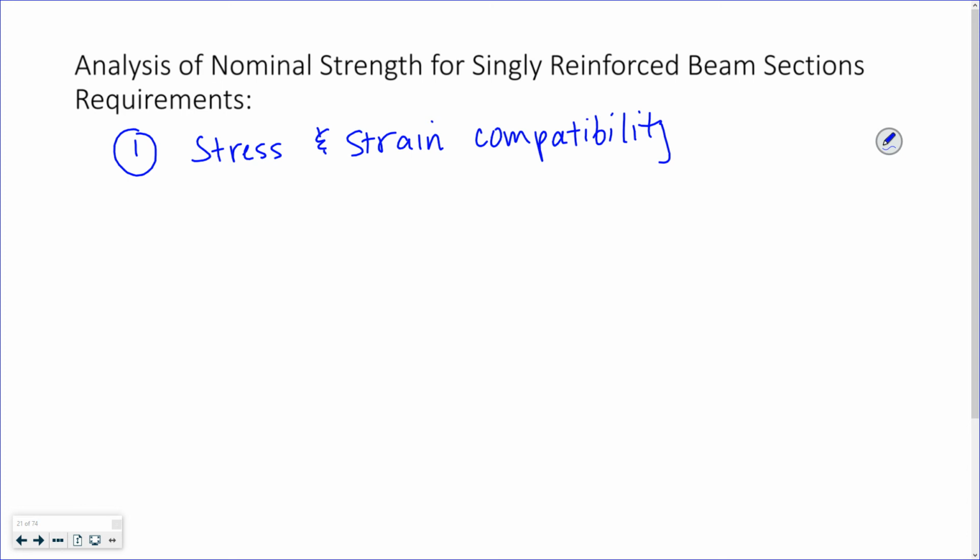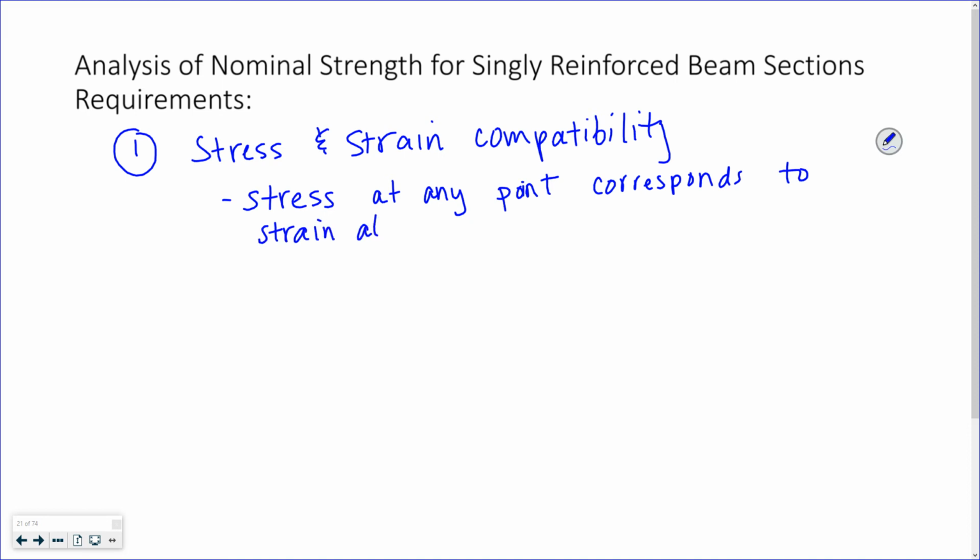And what I mean by that is the stress at any point corresponds to the strain at any point. And that would be following our material properties, our stress strain curves that we determined earlier for our steel and for our concrete.